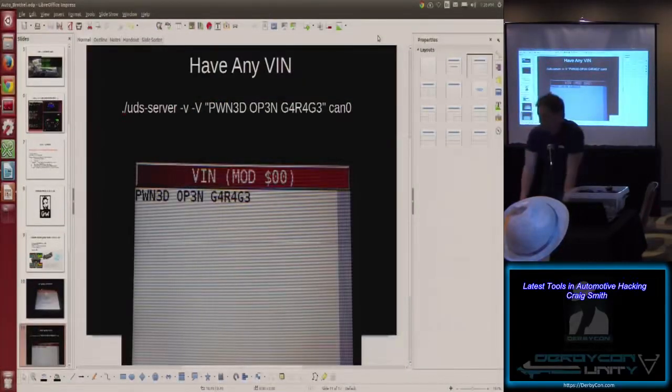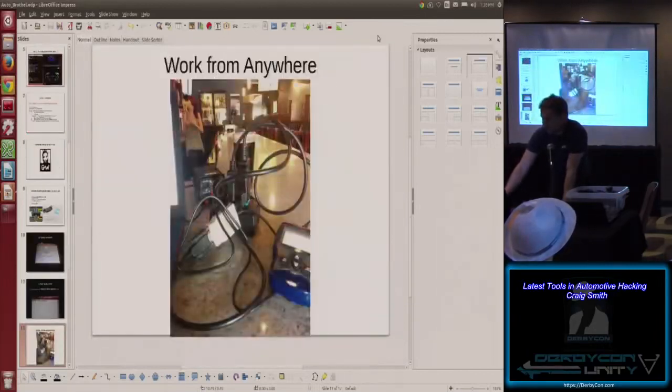So we'll do it this way. And so this one is, believe it or not, a valid VIN. It says pwned by Open Garages. VINs have a checksum in them on one of the bytes. In this case, it's the 3 in open. So this tool, if it couldn't do proper calculations on your VIN, that Bosch tool will error. It won't go through and make assumptions. This one's fine as far as it's concerned. It will try to process this one, no problem.